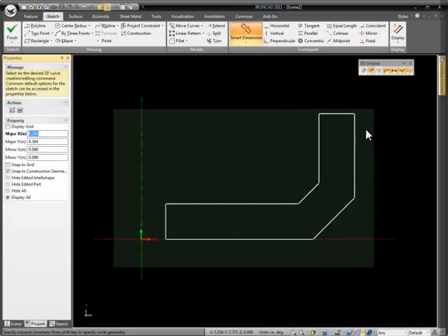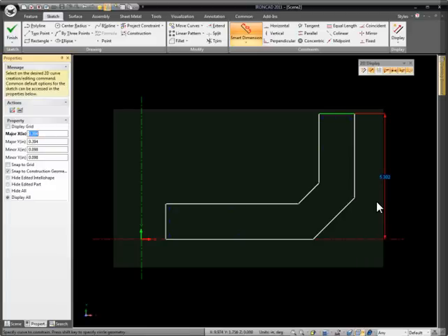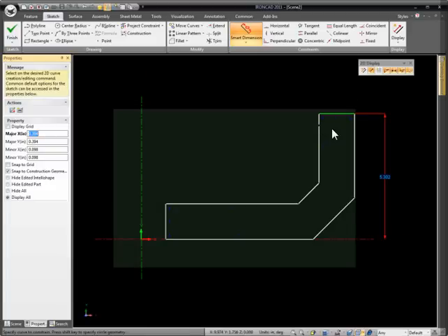And there's a key thing, you can actually pick on endpoints, or you can actually pick on curves to create your constraints. And there's different behaviors to both of those. Notice if I pick a line, and I come down and adjust this line, I actually pick the top line into our x-axis, we're actually defining that this is a well-defined constraint. Notice our curve element changed to be green, saying that this is well-defined in one of the degrees of freedom. So we can easily set that by using the actual line.